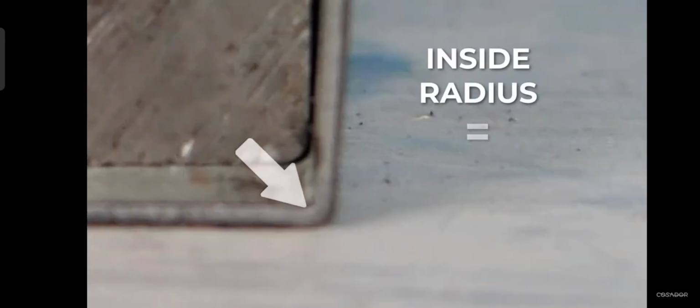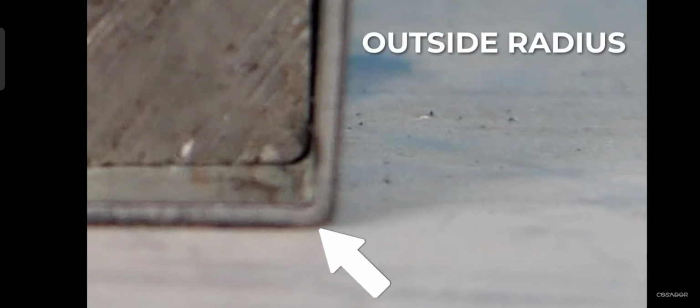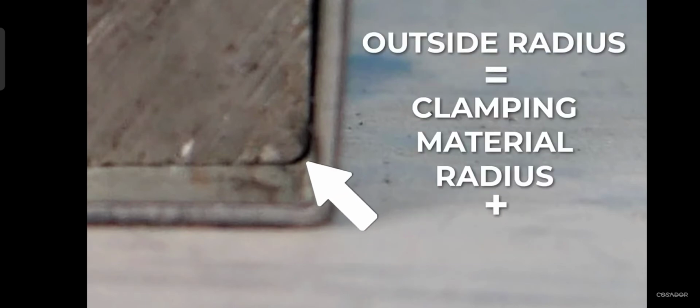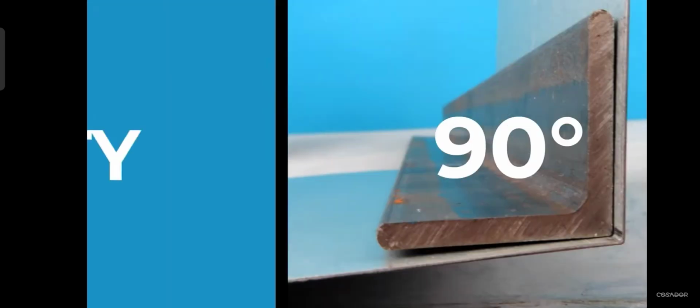The inner radius of the bend is dependent on the radius of the clamping material, and the outside radius is equal to the clamping material plus the thickness of the sheet metal being bent. So a piece of angled steel with a sharp edge is ideal for a 90-degree bend.